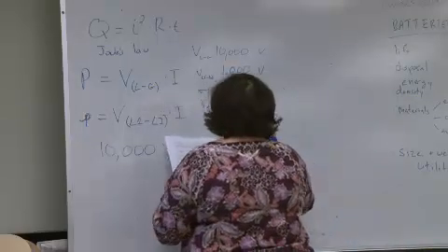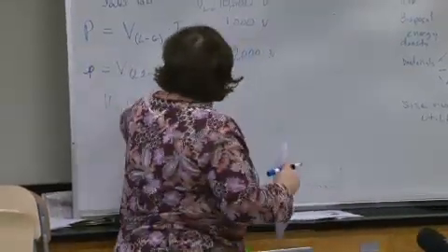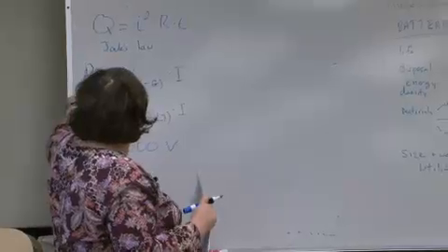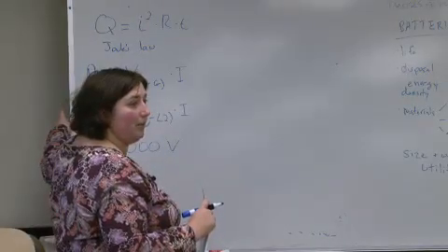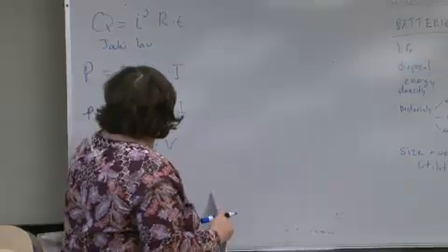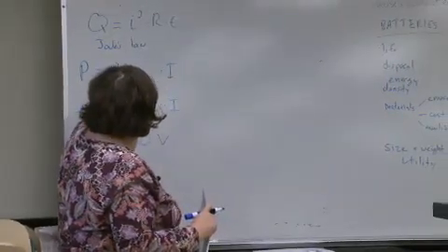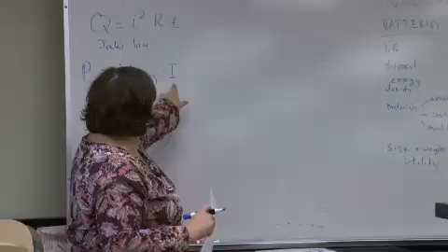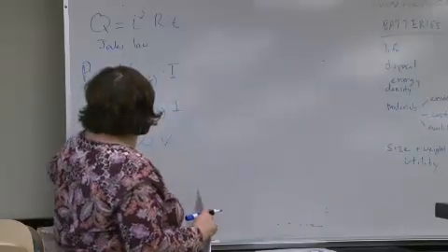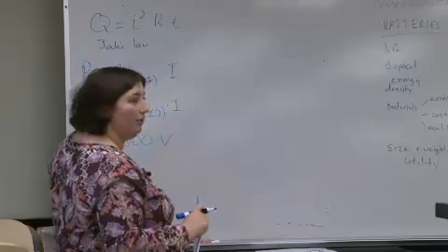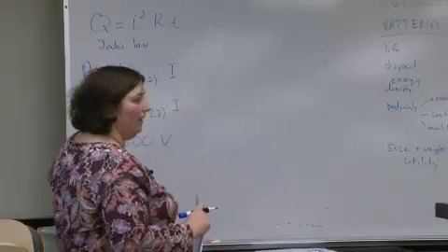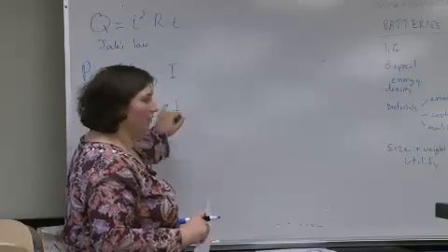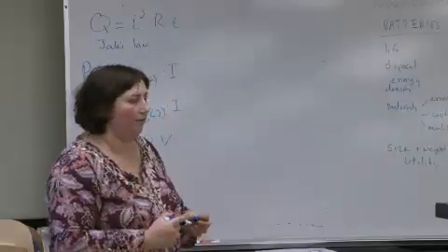Right. Okay. So we have these two equations. We're not going to worry about numbers right now. We want to maximize this P and minimize that P, right? And we know the relationship between these two V's. So if we minimize I, we minimize that power, which is good, but we also minimize this power, which is bad. And that's why we're trying to pop up the voltage to be as high as possible, so that we can maximize power and minimize our losses.